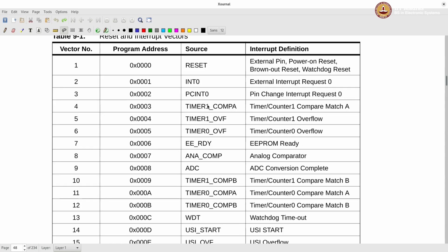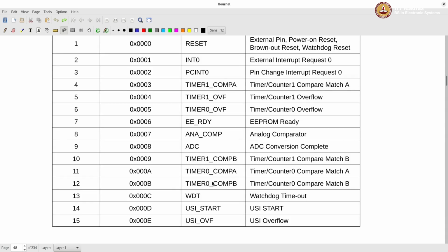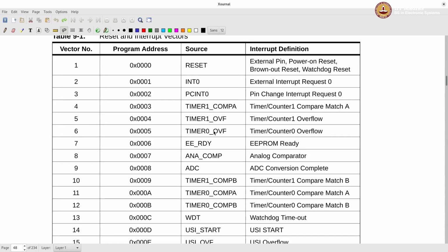You need to have an exit from every ISR. So you need to consciously do this, and all the ISRs should be properly software terminated. So let us do that. It's a very important step, and should be done in every application.